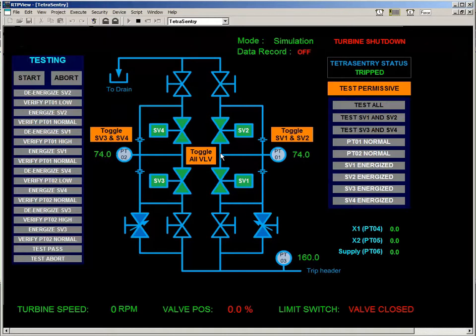That keeps pressure between the 2 valves in the serial pair to allow us to diagnose any problems with the downstream valve. In a situation where you put 2 valves in series, you never know if the second valve is going to hold the pressure if the first valve is closed and not leaking.